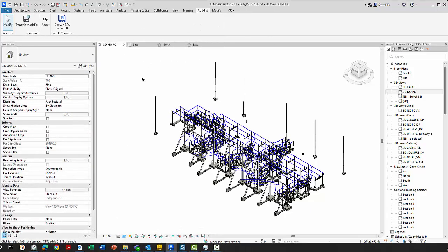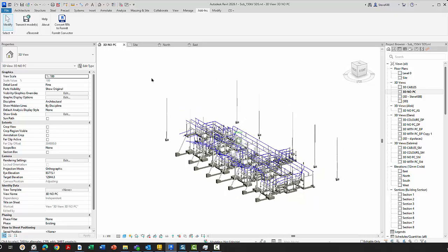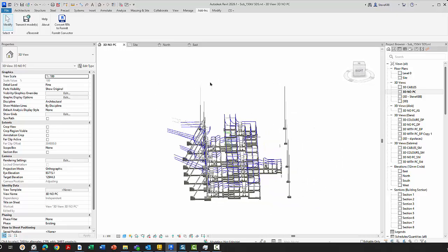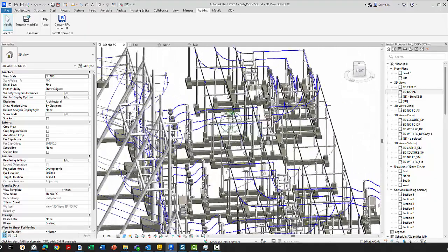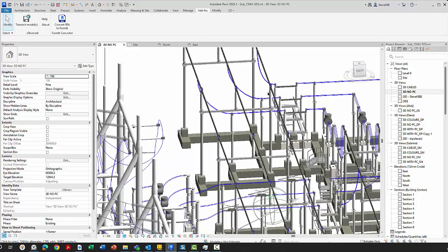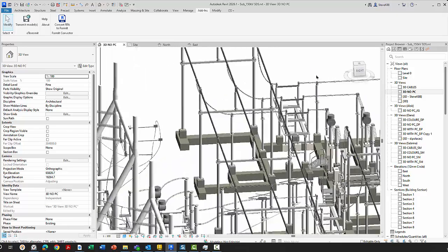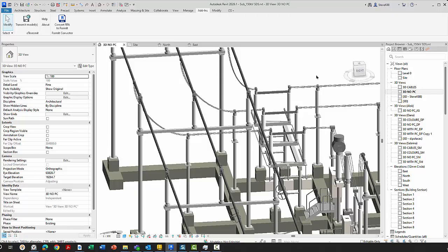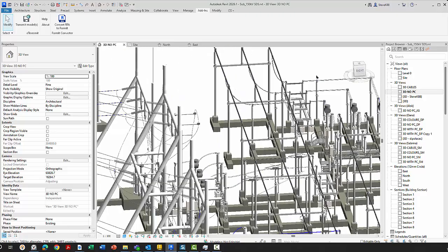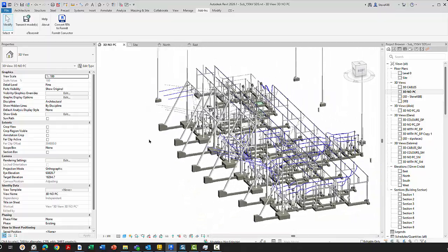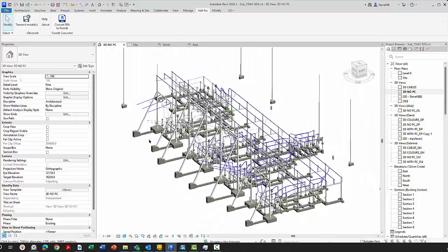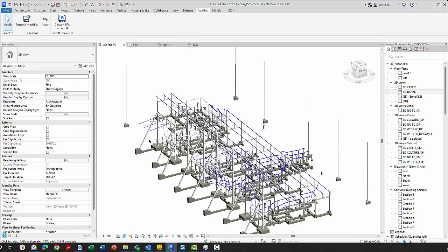Okay, here is a simple substation in Revit, and you can see the spacing between the lightning masts, and we can see the equipment is very simple in this station. Switches and insulators, CCVTs and such, and foundations. So we have structures, we have everything we need in this model. This is only the high side, it's only the high voltage side of a station.